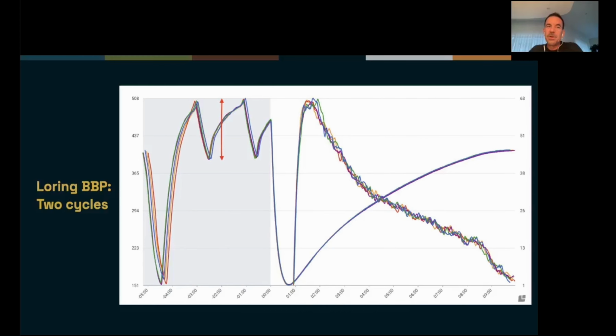Please note that extra conduction can also come from having the RPM level not be optimal. So if you're getting roasty flavors in a drum roaster, it's either that your RPM is off, your airflow is much too high, or your between batch protocol is giving you too hot of a drum. But we can figure that out pretty easily by looking at your data.